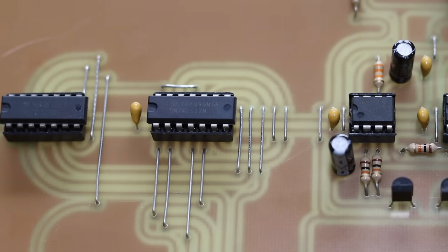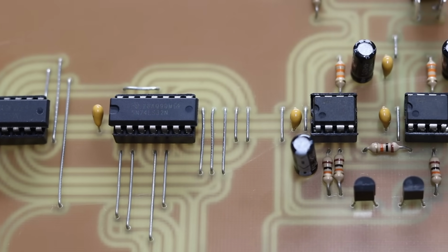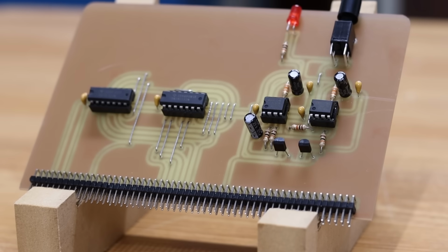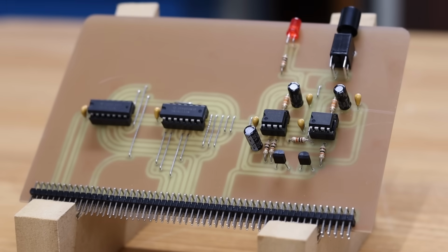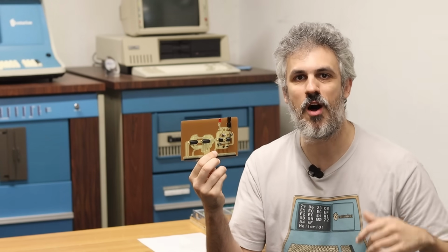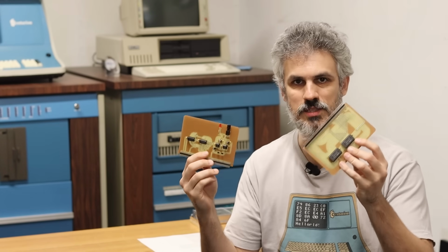And then we have our power on reset and a little reset button here that's going through the monostable multivibrator. And we have a little run LED up here. This is our very first blinking light. That should be on whenever the system is running and off whenever reset is asserted. Now, I haven't plugged these in and smoke tested them yet because, well, we need to figure out what program goes on these ROMs first.